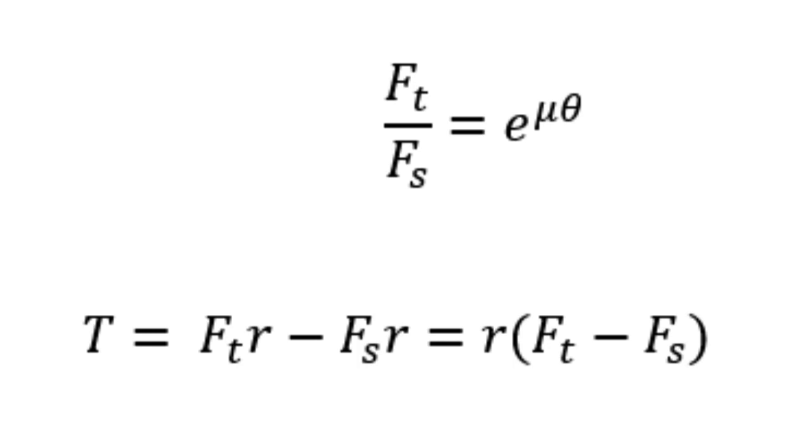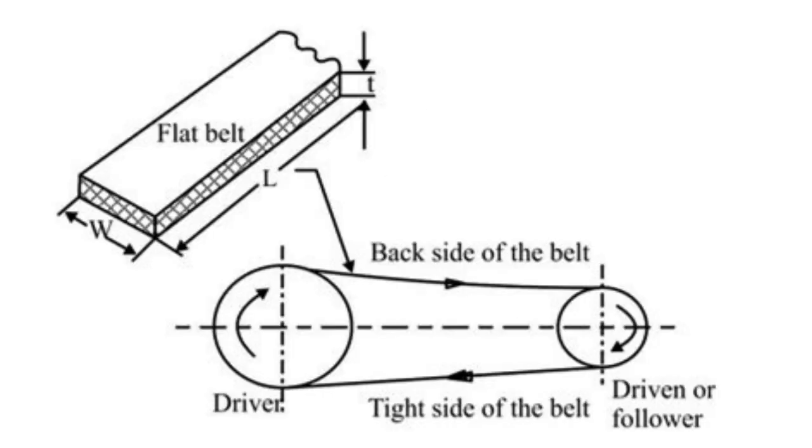Flat belt drives are used where power has to be transmitted for large distances between pulleys. The efficiency of flat belt transmission or flat belt drives is approximately 99%. The flat belt drives are simple, less expensive, flexible, and durable, and give better performance at high speed, give smooth operation, and require less repair and maintenance. However, they could slip and creep, and large power transmission is not possible.